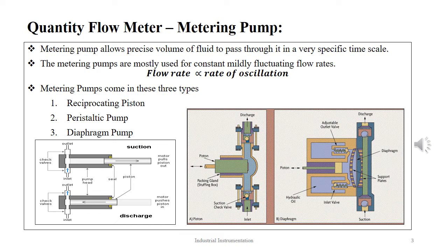A metering pump is a positive displacement pump which is used to provide a predictable and accurate rate of process fluid flow. Only those pumps which have very little internal or external leakage are used as metering pumps. Any positive displacement pump may be used as a metering pump due to its volumetric mode of fluid transfer. Metering is the name given to the precisely delivered adjustable flow rate. The term metering pump is based on the application and usage.